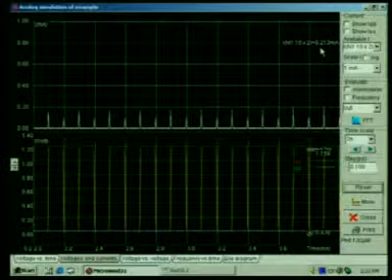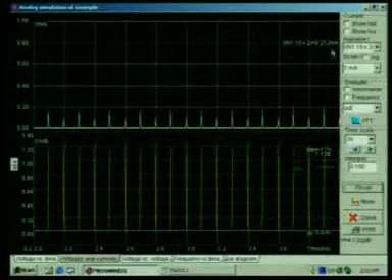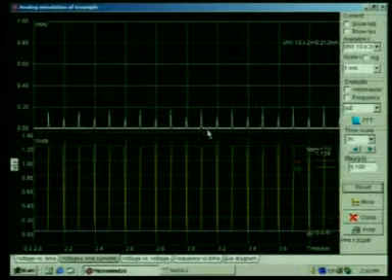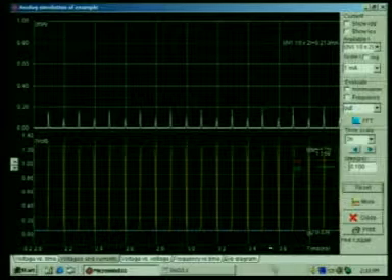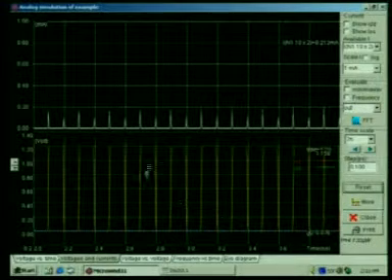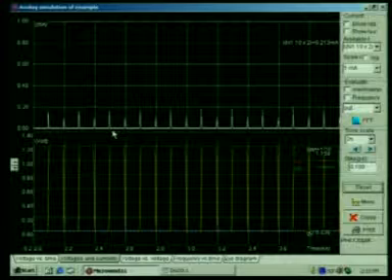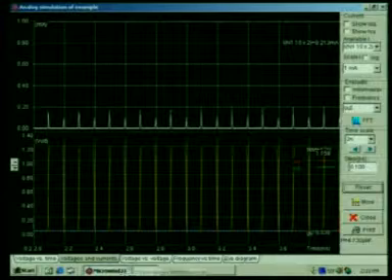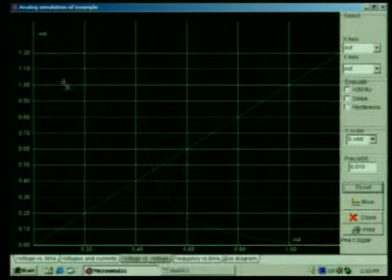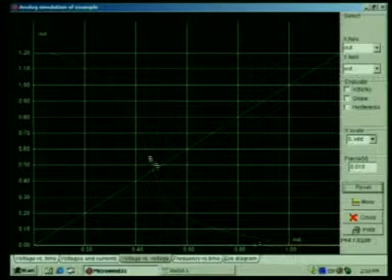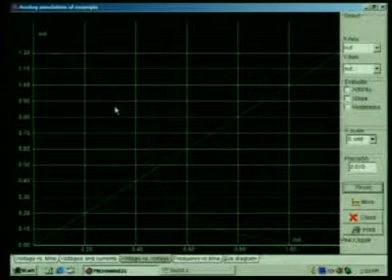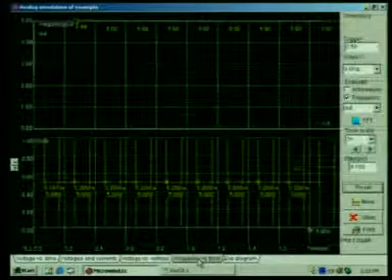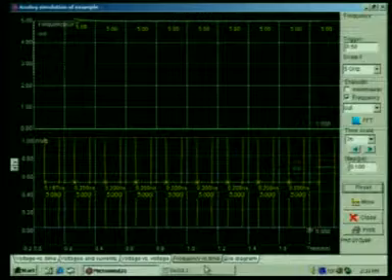This is the average current, 0.213 microampere, and these are the spikes during the transition when both P and N type are open. At that time there will be maximum power dissipation. So you can check out these spikes. Then voltage versus voltage, you can check out the characteristic, this one finally the transfer curve, and then this is frequency versus time.